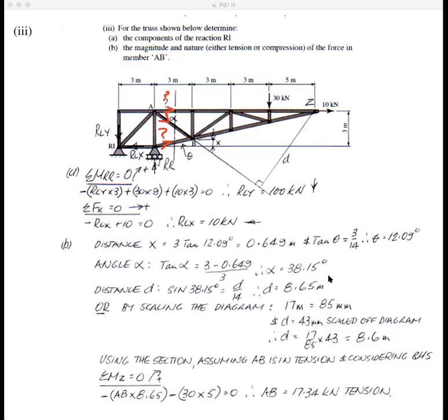Okay, thank you. I'll just go through this again by scaling. Look, that's fairly difficult, all of that, using trig, particularly when you're stressed in an exam. And this is a good technique. So what you do, I'll just go over what I just said. That distance from there to there is 17 millimeters, so you say 17 millimeters equals 85 millimeters. You've measured it. And then you construct this accurately, and then you measure that distance there.